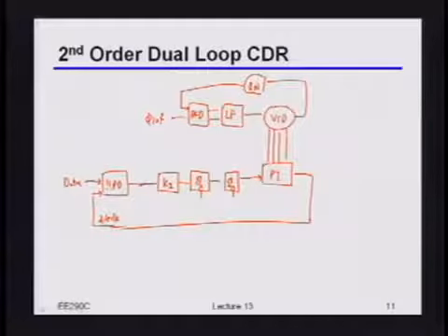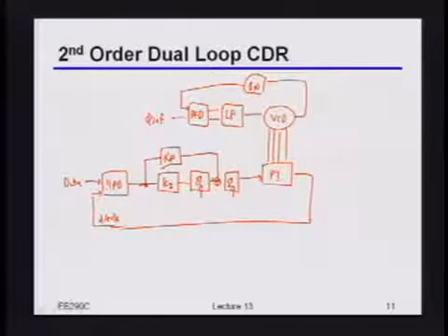Yeah, I have a feed forward path, and in particular, where does that get added in? From the output of the first accumulator. Yeah, exactly. So if I do this by direct analogy with a normal PLL, I'll have something that's usually called the proportional gain. And I'll have that jump around the integral section, and then feed that proportional gain into the last accumulator. Okay?